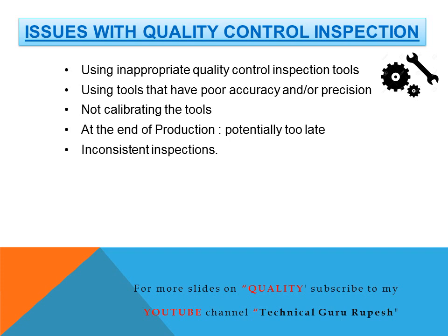And the third point is accuracy. We should do a good job by designing quality control fixtures that allow inspectors to check critical to quality points. The term here is critical to quality, CTQ, points quickly. But that is only applicable to the products that will have to be checked many times. The very first is to set up the right process control in order to minimize variation in the product attribute. This is what I discussed, that this can be done during inward inspection or receiving inspection also, but that should not be done at our end. That should be done at our supplier's end.